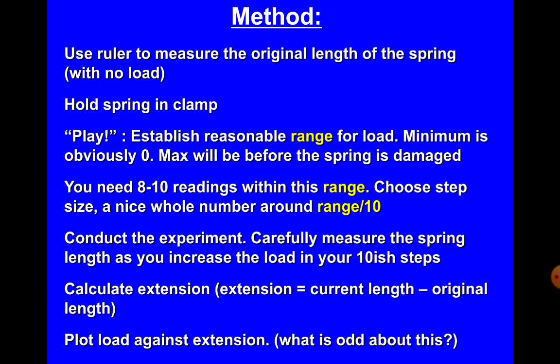Conduct the experiment. So for example, you start with 0 grams, 50 grams, 100 grams, 150 grams, 200 grams, etc. Okay, don't mix up that. We need to know the extension. That means when we put a mass or a load on the spring, we find the extension by the current length minus the original length.